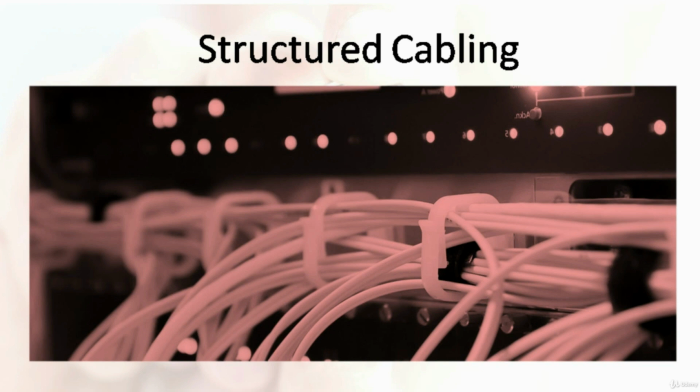For the cables, the most important parameter is its characteristic impedance, and these are split into categories as stated in the ISO standards. Without going any deeper, you only need to know that the only ones you need are category 6 or 7 cables, with the most prominent being 100 ohm characteristic impedance of these categories. Now, if you want to learn more about this, you should get a copy of ISO 11801 for more information.